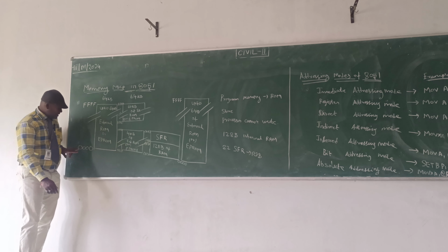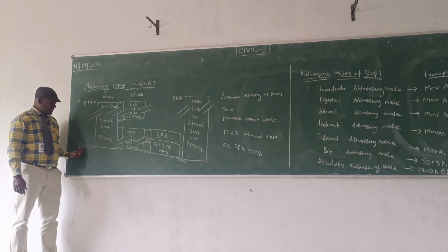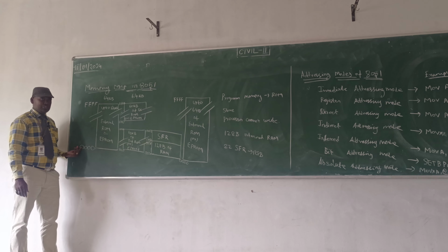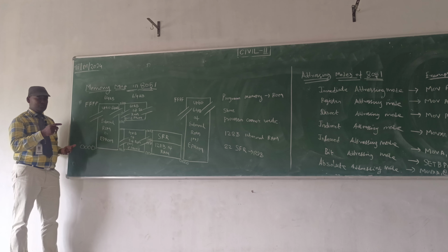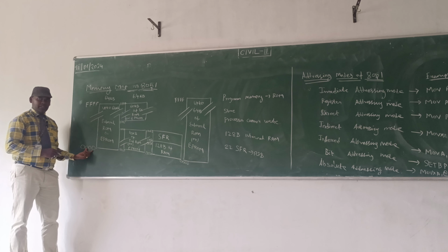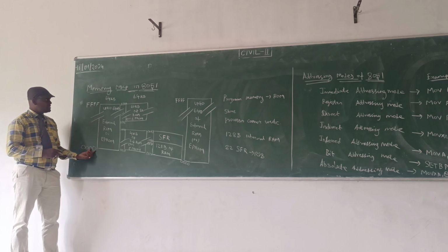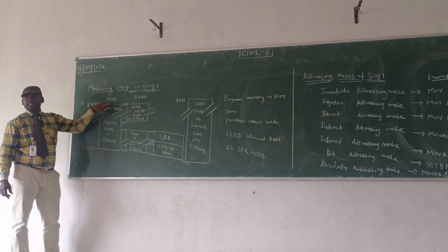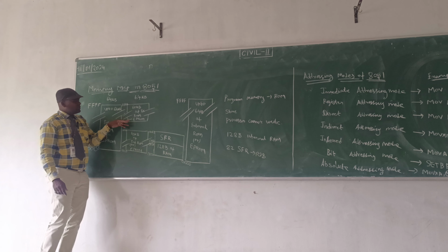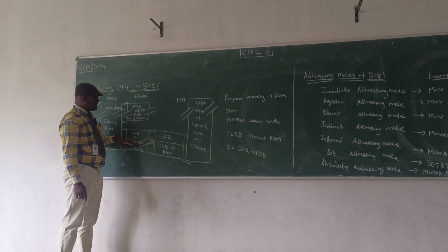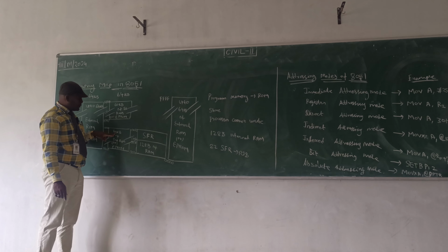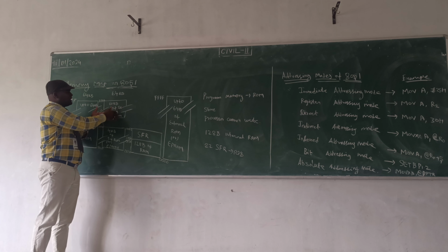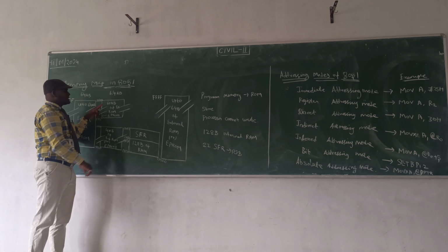You all know that. So here, each hexadecimal digit represents 4 bits, like 0000. Here we start; it is the initial stage, and that is the maximum capacity, the maximum storage limit of 64 KB, right? Here you see the 4 KB internal ROM, and the external ROM we can extend up to 64 KB.